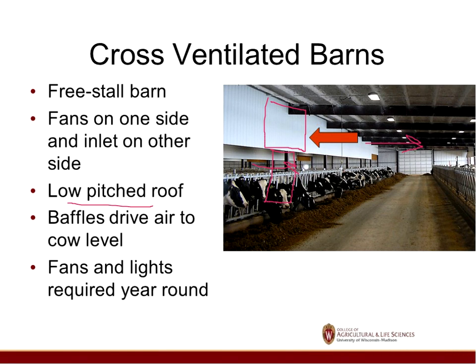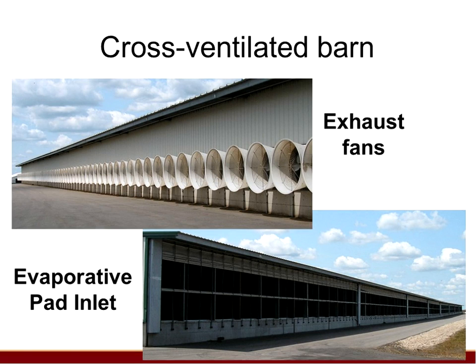Now, one concern is that we have to run fans and lights year-round in these buildings. If you have curtain sidewalls, you can open them up, but you can't in these types of buildings. So we've kind of roughed out here in Wisconsin, it's going to depend on where you are, we'd use about a third more energy with this type of building than you would with a naturally ventilated barn with stirring fans. However, you really have to look at what the milk production increase is, and we haven't had a good study on that to see if the milk production increase covers the